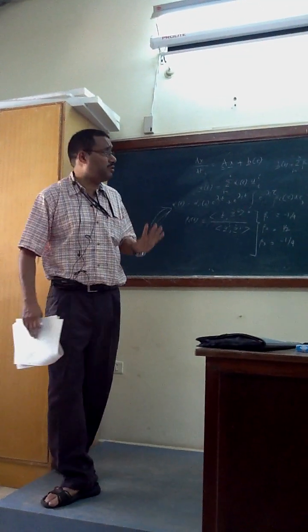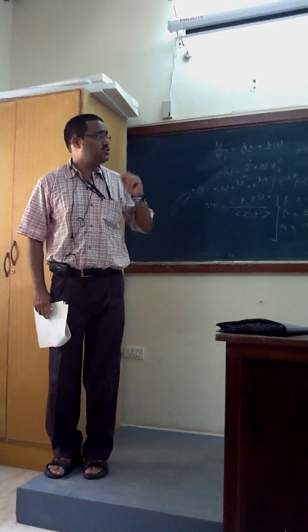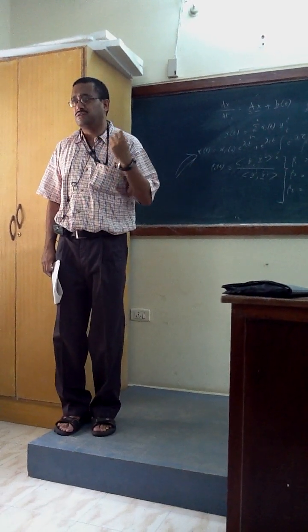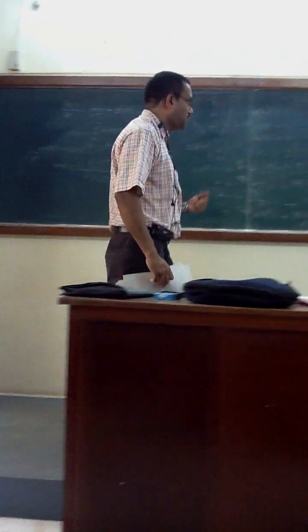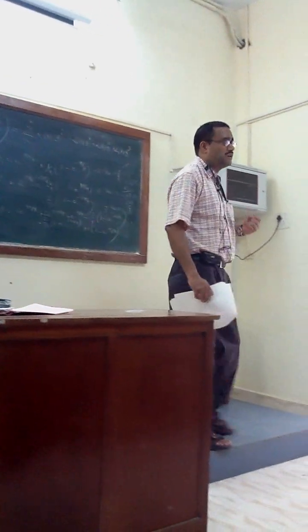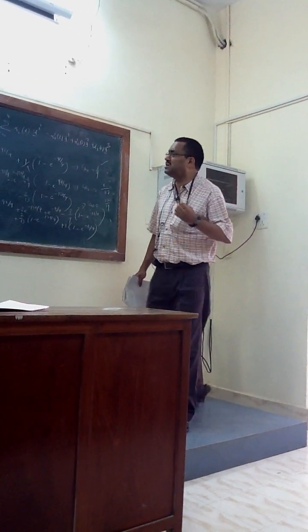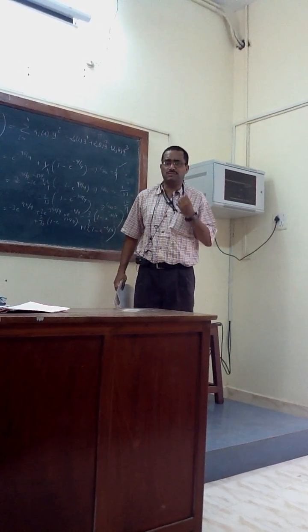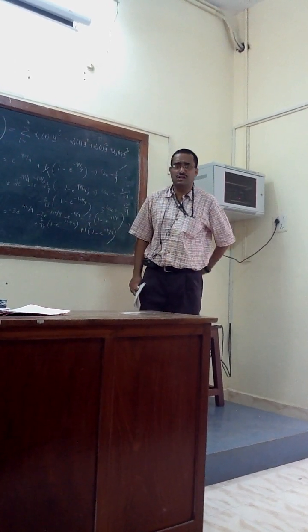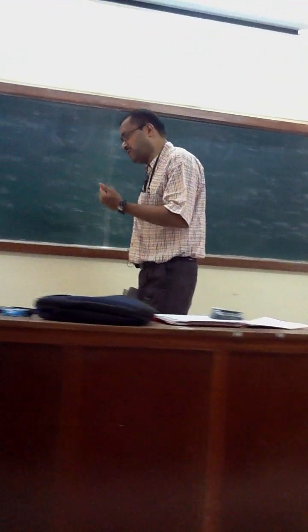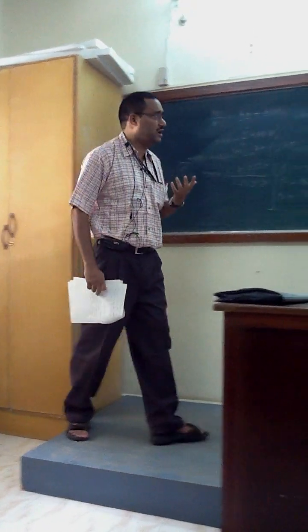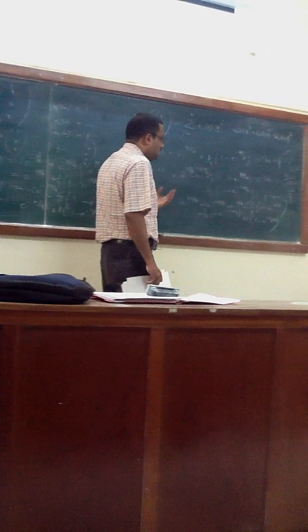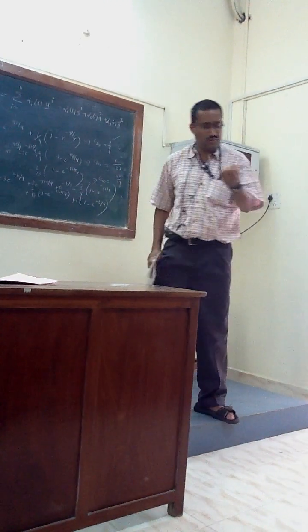So now if we look at these numbers and the AX equals to B solution, this is a complete problem. What we have solved is one of the most generalized kinds of problem, AX plus B with this kind of thing, and this will be quite useful when you solve many such problems. But this is one of the real chemical engineering problems we have solved, which is nothing but A going to B going to C. This is a very simple reaction, but you see how many complications there are. In this simple reaction, A goes to B, goes to C. Here I wanted to see the time dynamics, the time dependent profile, and not only that, the steady state problem, and that leads to this kind of interesting episode.